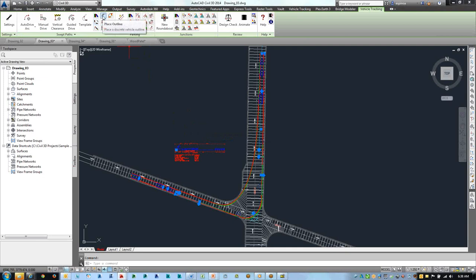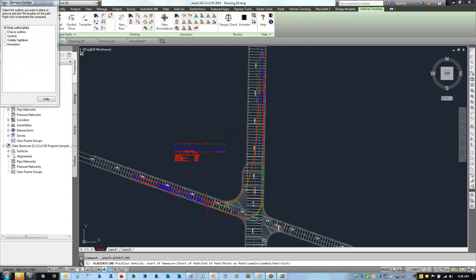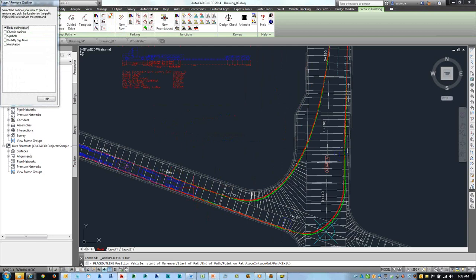the drawing outlines of that vehicle. So over the course of its path, I'm going to place this outline. So now you can see that I'm in essence dragging a copy of that vehicle along. So right up to about here, I'll place a vehicle there. I apologize for the color blue there, but it is then placing that vehicle going through this turn. I'll bring it up to approximately right about here, and then drop this down right about here.